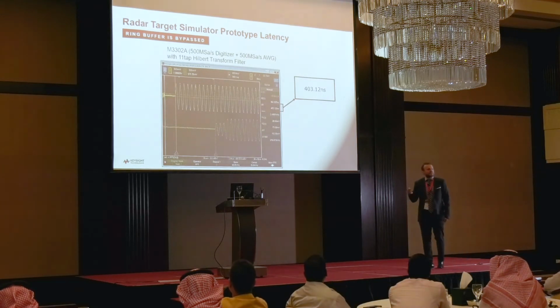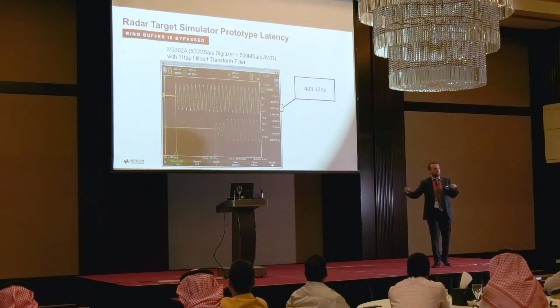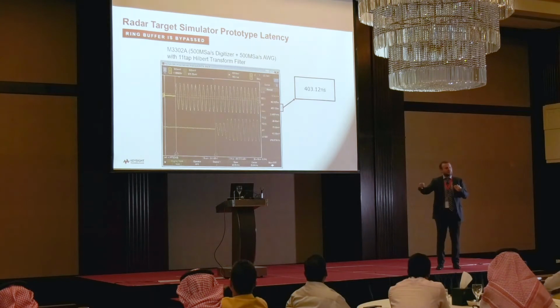And 400 nanoseconds at the speed of light is equivalent to 120 meters. So that means we can simulate a target that is at 60 meters away from a radar system, and that's pretty close.